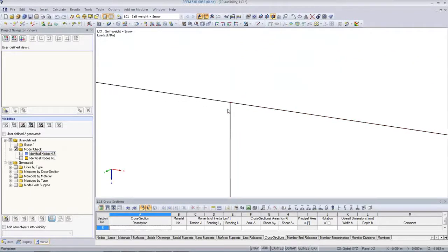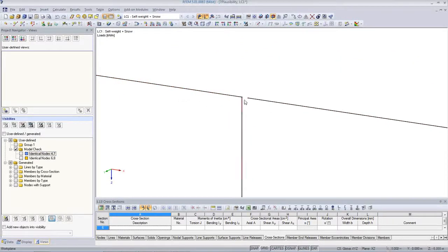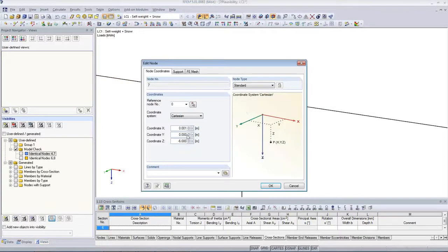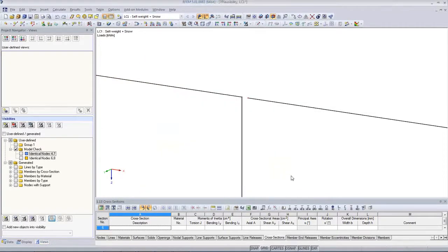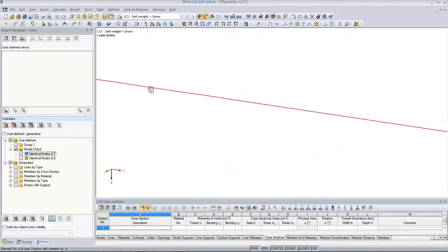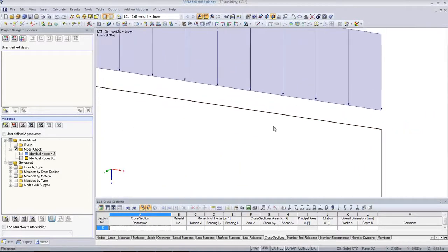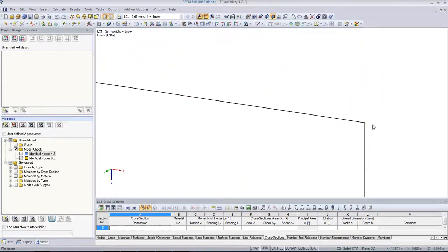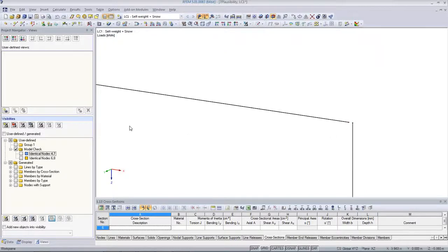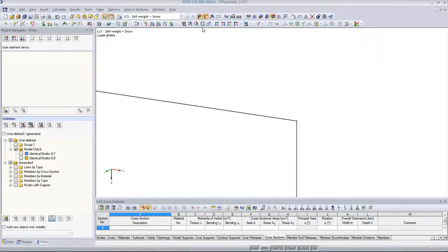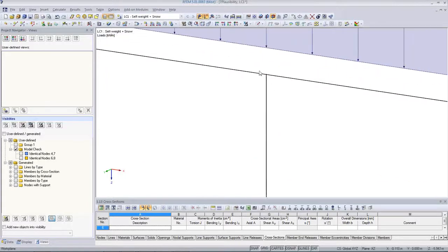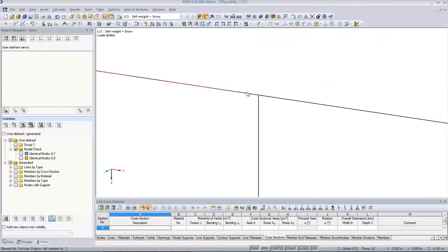In here. So I have to go down closer, and I see here now there is a problem. We have the coordinates, we have 1 millimeter of difference. And the same is on the other end of the structure, where we have the same problem. Okay, how to solve it? I can either drag and drop the node. Also, not every software can just drag and drop such a node and connect it this way.